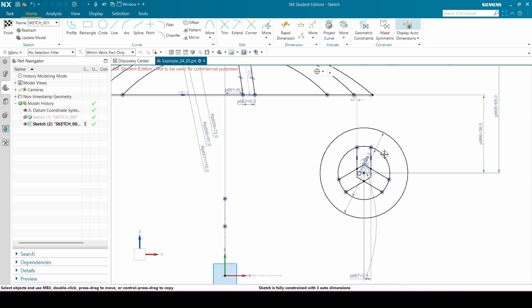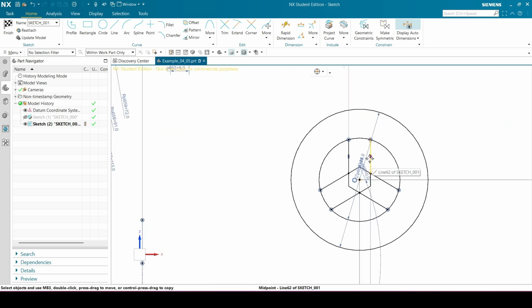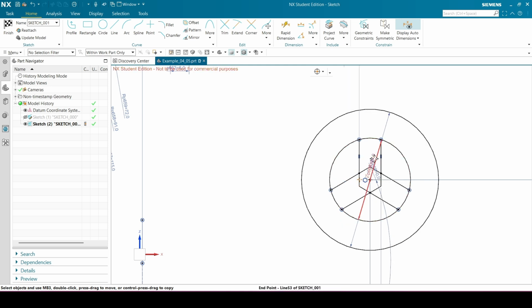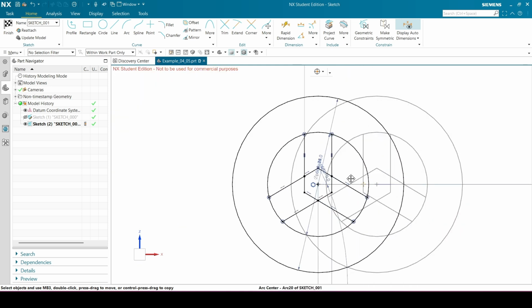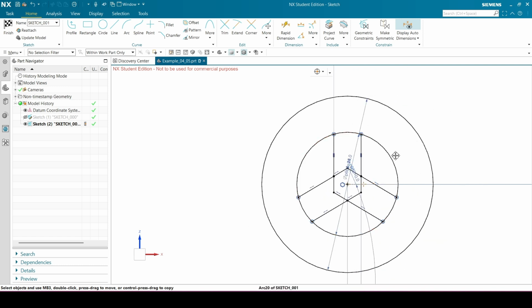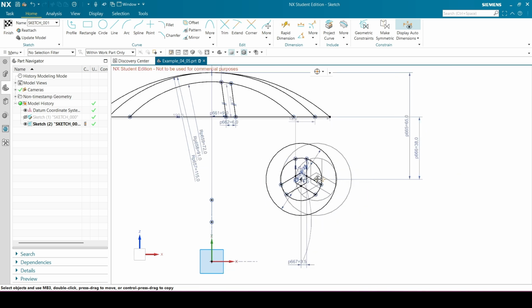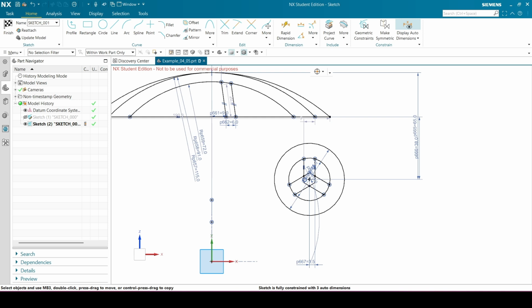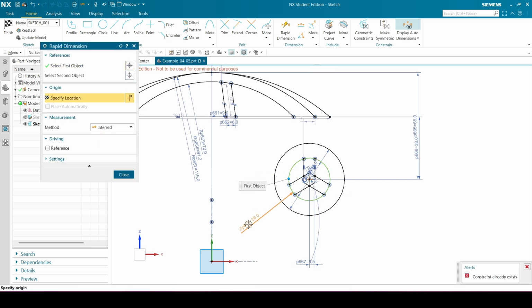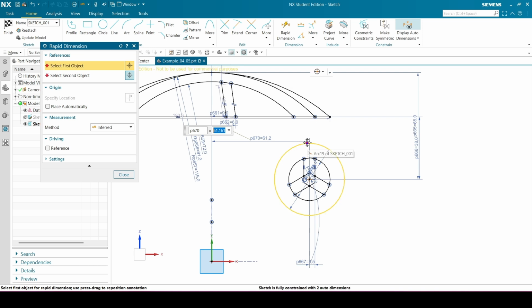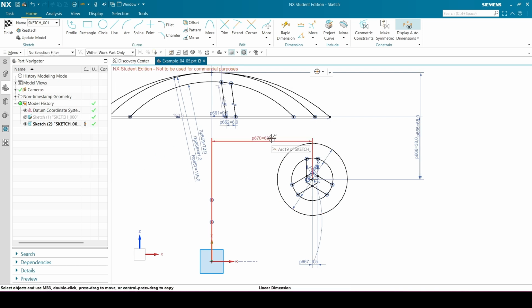Okay, so just to test whether my wheels are actually fully constrained, you can pull at all of the lines, and the only way it moves is in this dimension, nowhere else. So basically I just need a dimension to constrain it in this direction, and there is one. It is this 63 millimeter that was given, between the center point here and the sketch origin here, so that would be 63 millimeters. Okay, then the wheels are constrained.